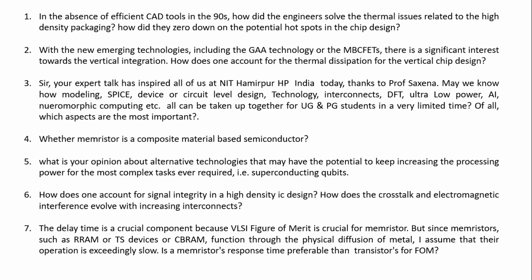So what do you do? You put a buffer in the middle, ground wires or power wires. In an integrated circuit, you do exactly the same thing. If two signals are clock signals, it will be good to use power or ground wiring in between, for instance. And there are lots of simulation tools to monitor crosstalk, electromagnetic interference, etc. So CAD tools are essential to do this sort of thing.